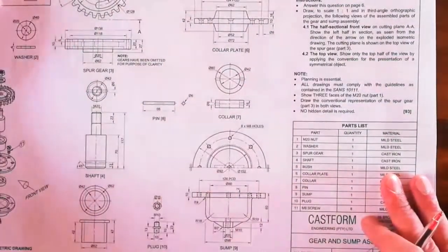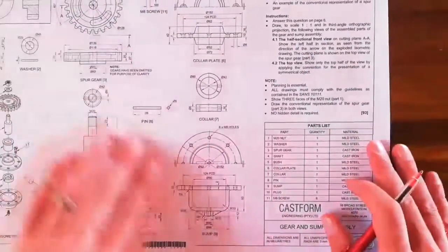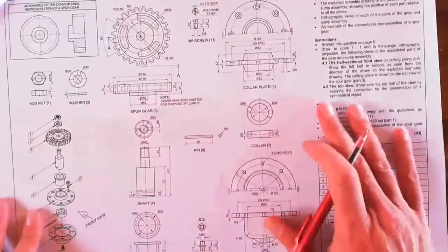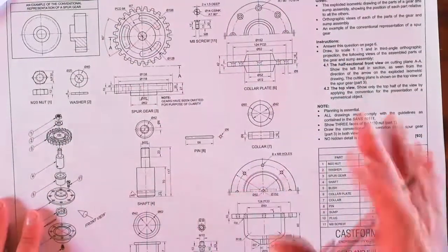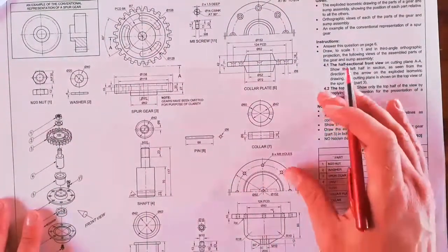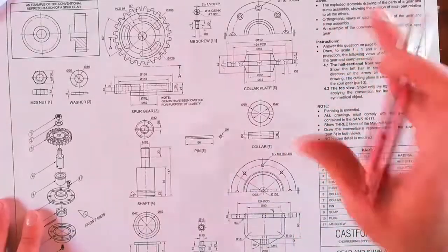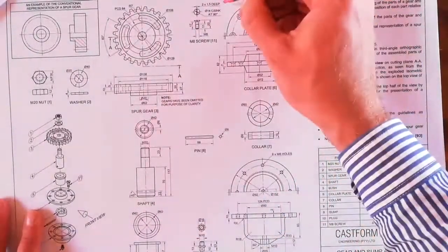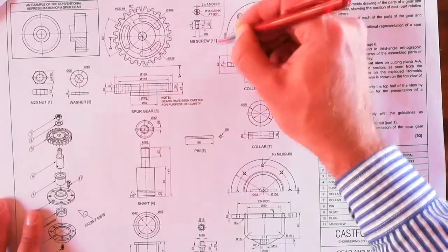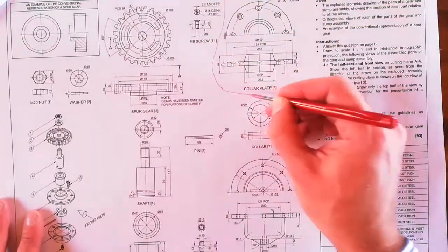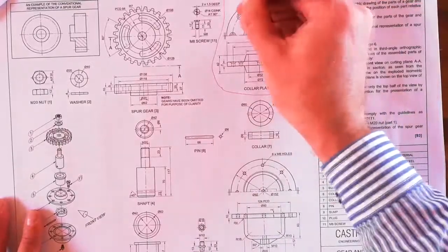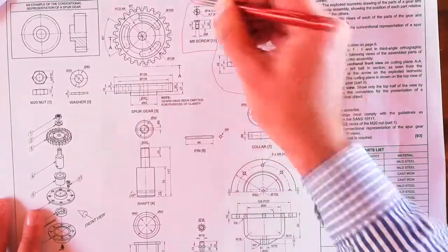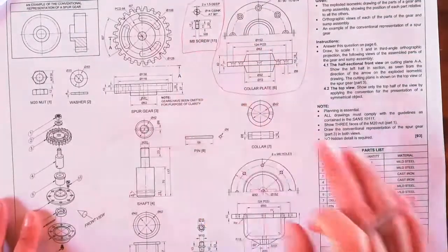Okay, let's get to the casting. We'll do an in-depth discussion of the mark allocation in a moment, but this can so easily overwhelm you. But what you need to do is, remember it's third angle orthographic projection, but they're grouping the different parts. So just take even a pen if you have to, and just group for yourself what goes with each other, just to not confuse. That's a separate part from these two. Although they're very close to each other, it's a separate part.